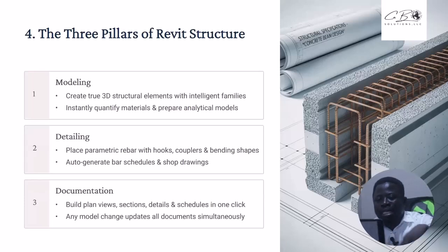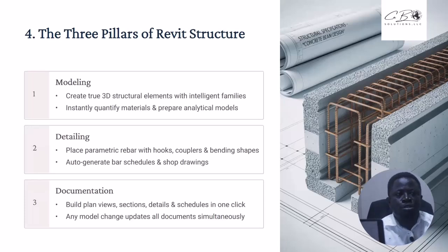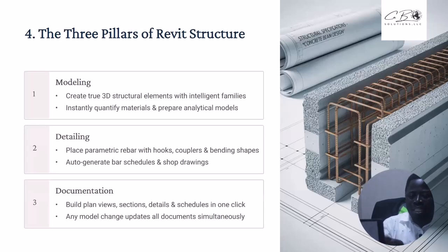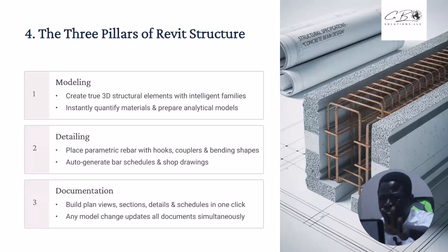When they give you a 3D Revit architectural model, they expect you to also give them the structural model so they can fuse your structural model into theirs. Know the column position, the sizes you have recommended, how your beam depth affects the ceiling, how your column eats into their living spaces.